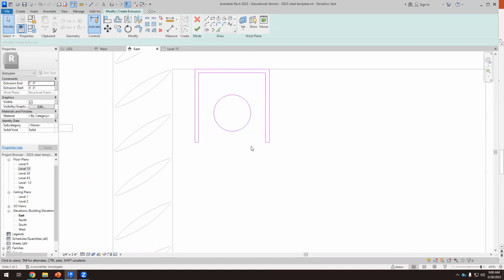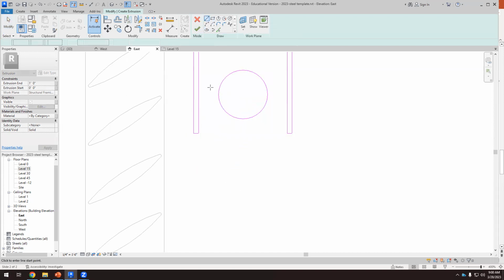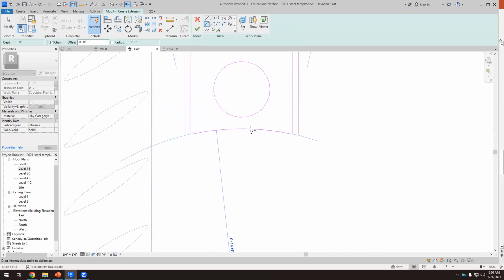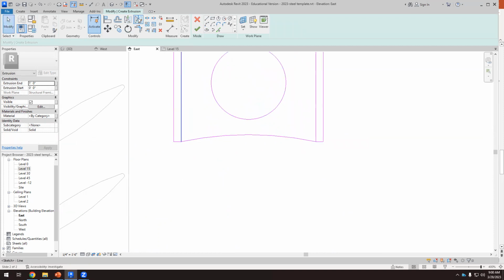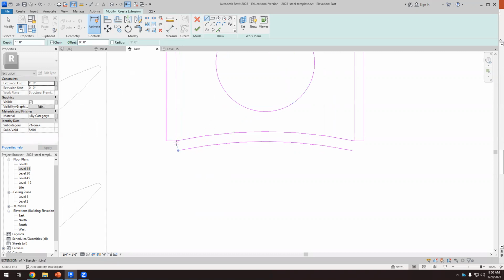And now I'm going to create those shapes for the louvers. So I'm going to use this start and radius arc, this and this, and I make it that shape here. And now I offset 1/2 inch, 1/4 better. And I close the gap here and there.